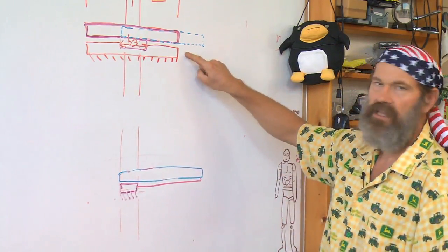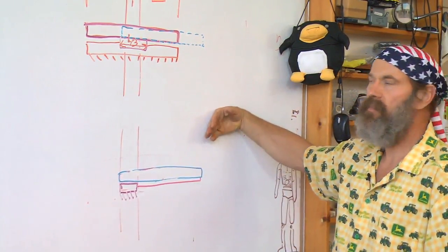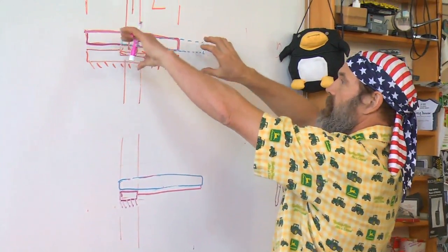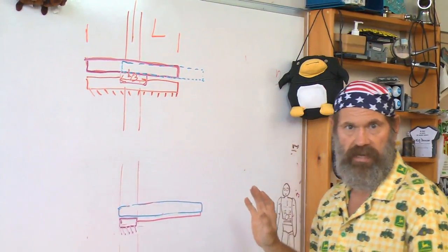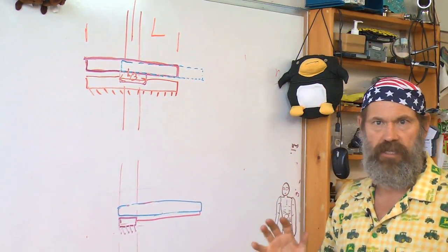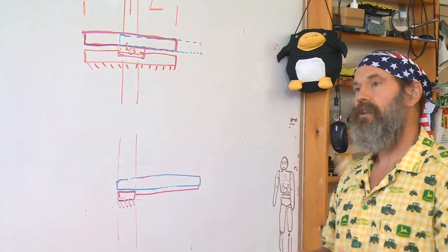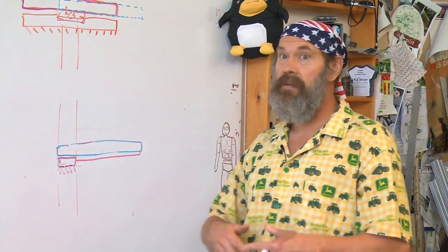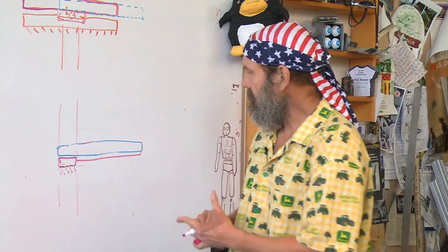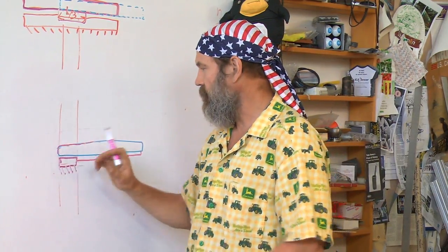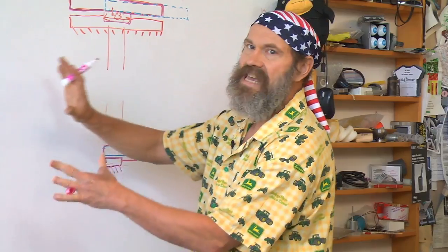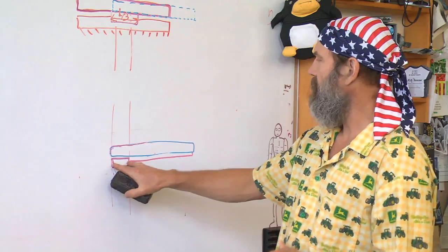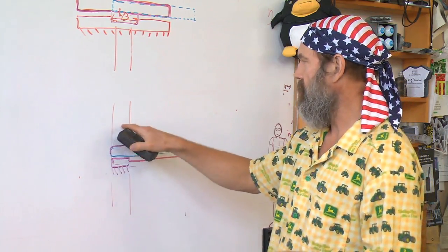See, this is the opposite of that, the reciprocal design. There are cases where this is better. You have more bearing blocks. It's a different design like a regular machine tool bed, but this is a drill press. It doesn't need the same stiffness and accuracy of a milling machine. If you needed the stiffness and accuracy of a milling machine in your drill press, it would become a milling machine. So right away you see, by thinking things through with these simple sketches, we're laying out what our machine will be, that this block will be attached to the column.